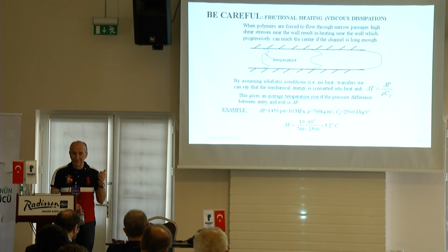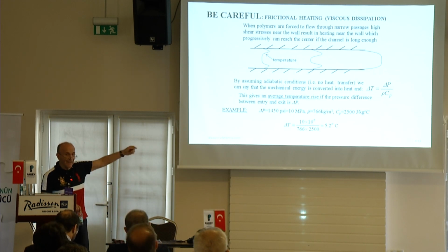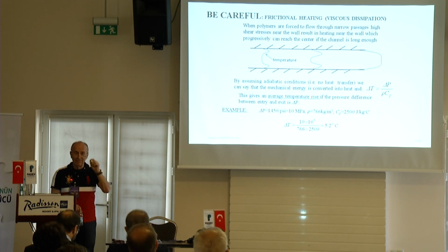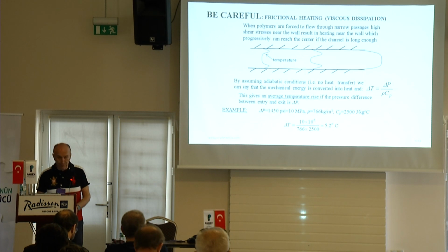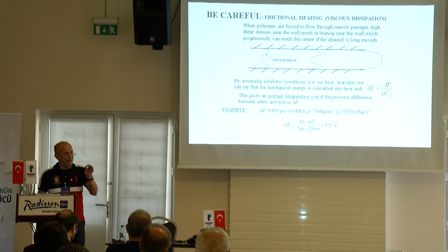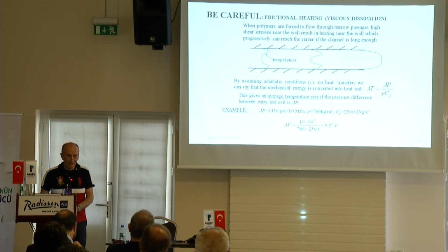They had this kind of profile, locally very, very high temperature, and they did not know. Then they modified the process, and they solved it because they knew what was happening. So you can have locally very high temperature. It can be not just 5 degrees, it can be 20, 30 degrees. And if you have a temperature sensitive material like PVC, you're going to have local degradation.